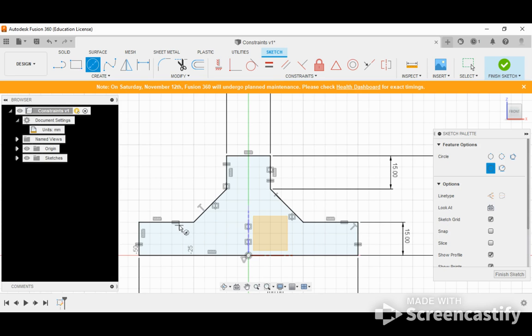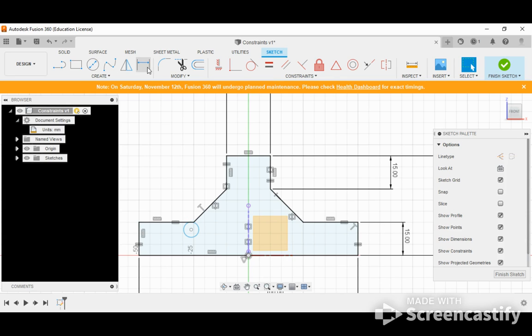I'm going to put a circle here somewhere. Okay. That dimension is 5 millimeters. And the instructions actually say that when you draw the circle, the center should meet the following constraints. On a vertical line through the intersections of lines 3 and 4. These are 3 and 4. So this needs to be vertical to that.